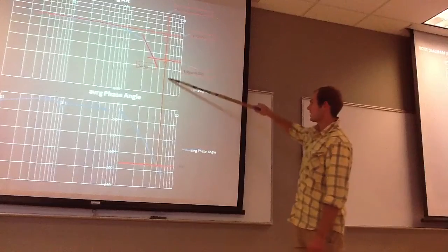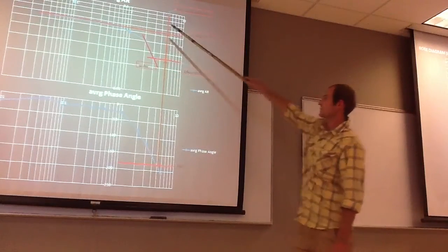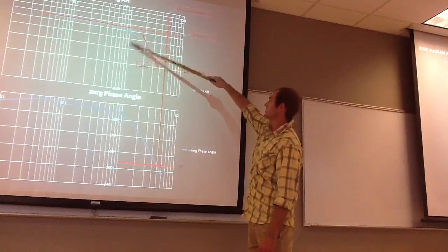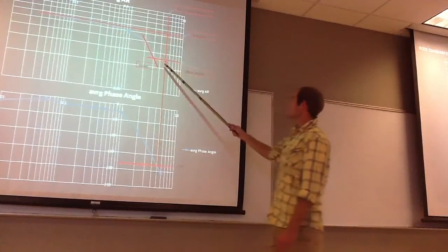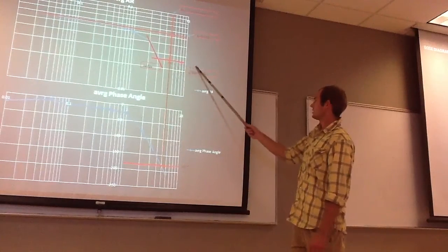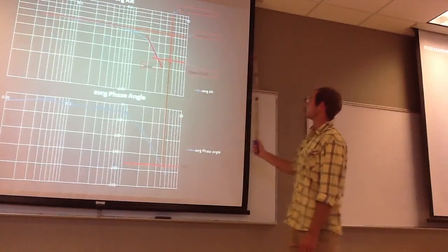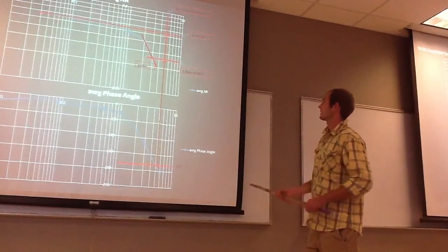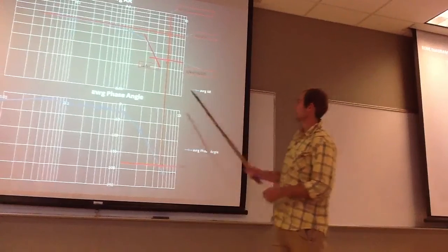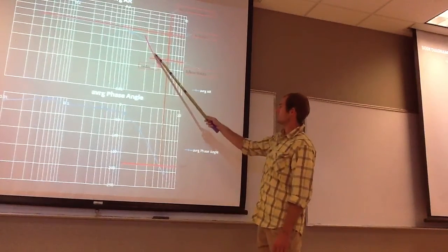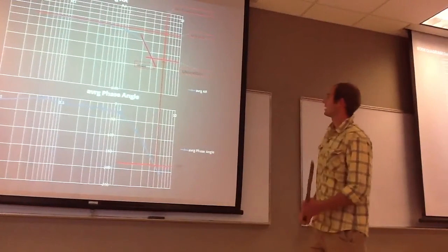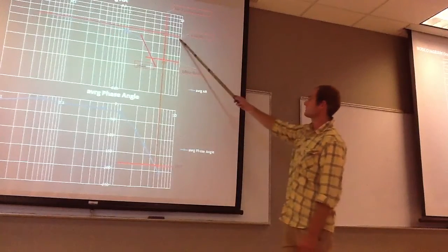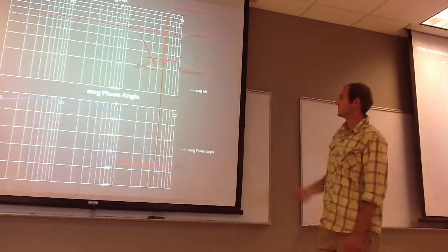We go up and cross into our amplitude ratio versus frequency to find what our 1 over KCU value is. And we find what our FU is, which came out to be 7 here, which is fairly high. And our order was the slope of this line. And our K value is represented right here of our amplitude ratio.